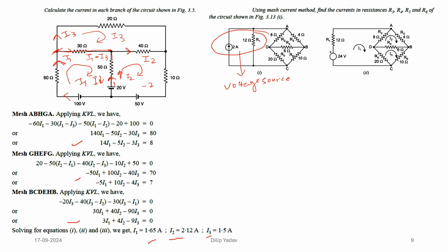Now we will form I1, I2, and I3. That means the current flowing from the circuit, I1, is going this way and it is distributed into I2. This will be I2, and this is I3. So how are we going to solve it? We obtain the KVL equation, that will be 12 I1 minus 8 in this, and we obtain the first equation.